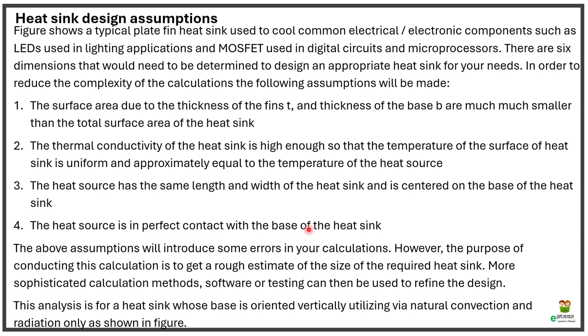So the above four assumptions that we have considered will introduce some error in the calculation. However, the purpose of this calculation is to get a rough estimate, and as we discussed, this rough estimate can be verified with software or testing can be used to refine the design. So finally, we can make one prototype also, and then this fixing will be tested and verified with the calculations. So that will be the actual verification. So that will confirm the design.